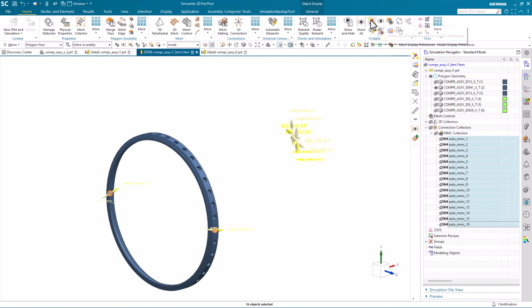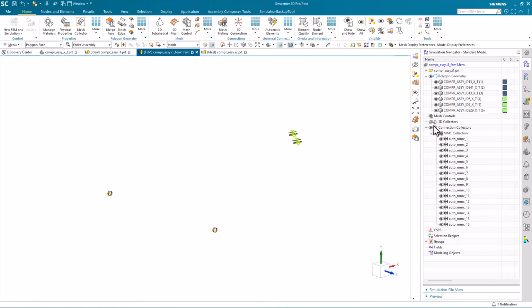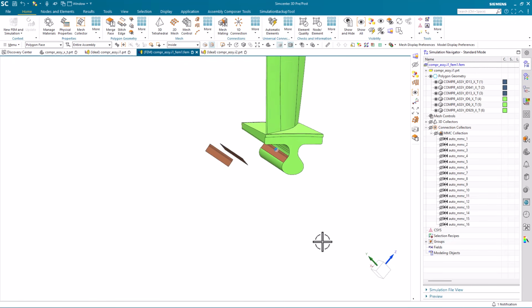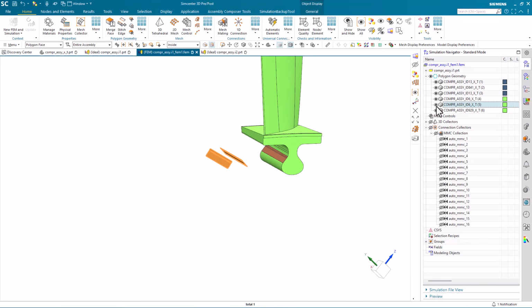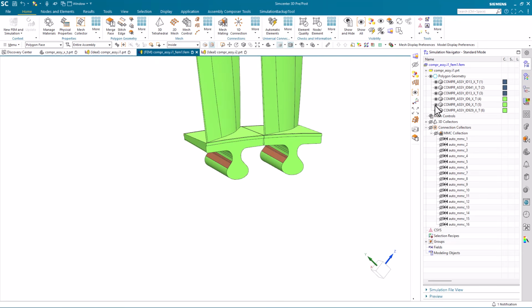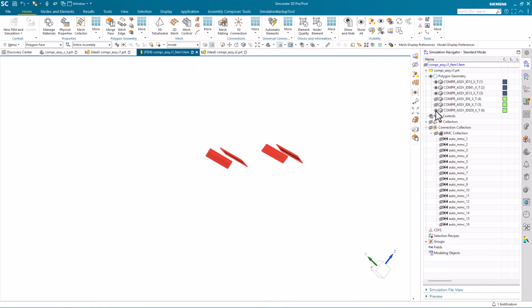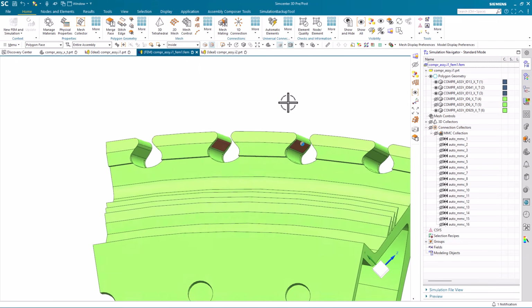So I'll show only those mesh mating conditions again. Focus on the area around the compressor, the blade at stage 3 of the compressor. So here, again, in a similar fashion, I can highlight the bodies. So that first body is indeed a blade body, and the second one is the second blade, and that last body is going to be the disc associated with that stage.